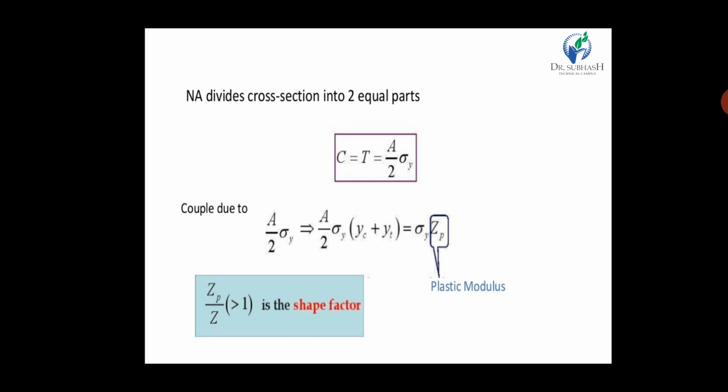Now, a few of the disadvantages. There is little saving in column design, so that's why we are not introducing it for columns. We will introduce it only for beams and portal frames. The second disadvantage is that it is difficult to design for fatigue, and the structure is complicated. It is difficult to obtain the collapse load.